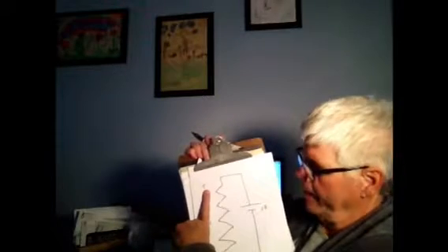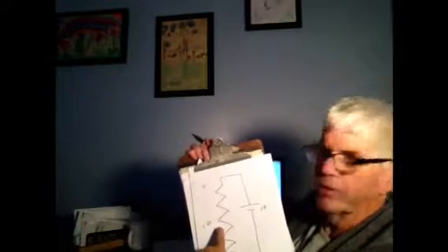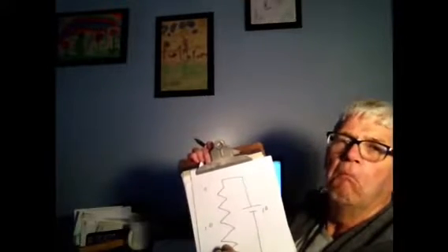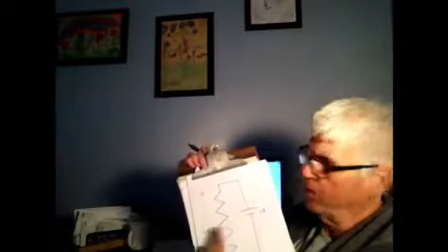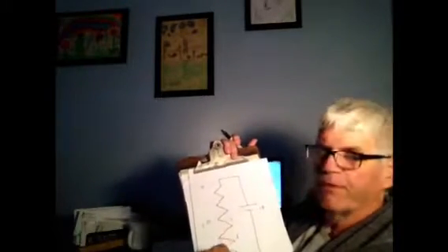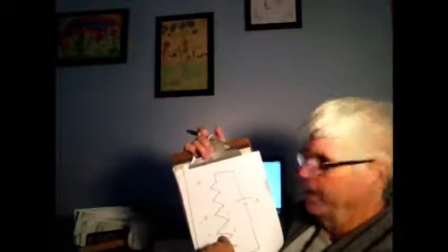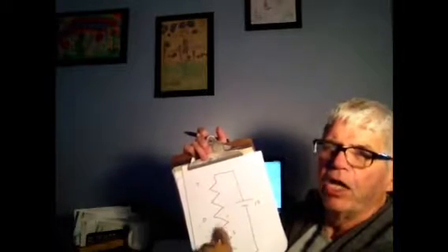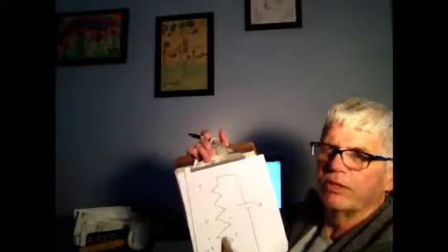Wonder how much voltage we have across, say, half the resistor. Half the resistor. Turns out we've got half the voltage across there. We've got 5 volts, or half of 10. Wonder how much we have across 1/4 of the resistor. Turns out we have 1/4 of the voltage. In other words, this voltage divides pretty much evenly along the length of this resistor.